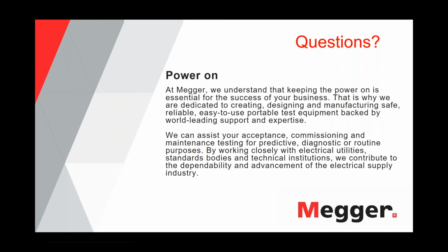So it is typically recommended not to touch the cable with 10 delta before it even reaches a year of age. So whatever you measure in this first few months to a year, or maybe a year and a half, depends, can be misleading. And then you might be in the situation that you do incorrect decision making because your 10 delta values are off.